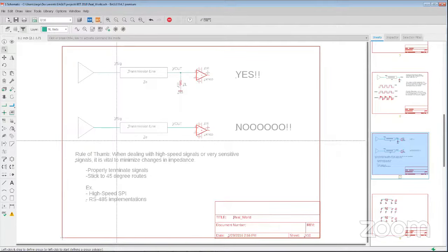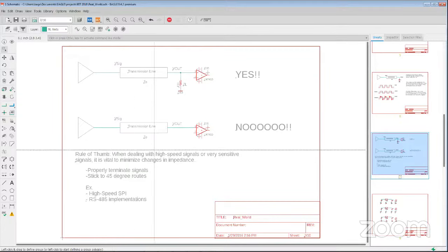So even if it's something that visually looks short to you, let's say an inch-long trace. If you're running USB-C, 2 millimeters could cause an issue if you don't account for it right. So you want to make sure to be aware of the requirements of the protocols you're using.